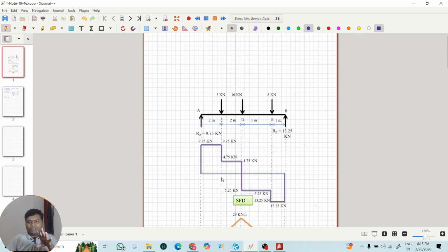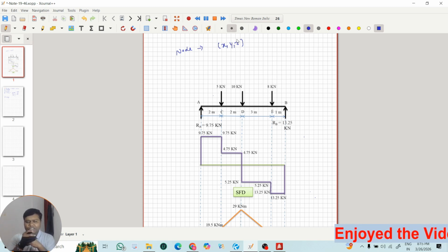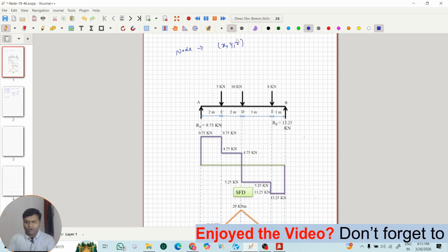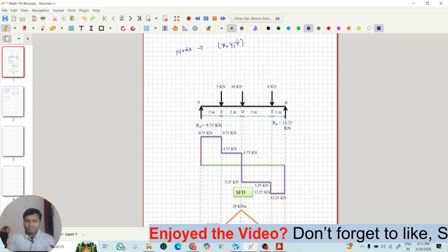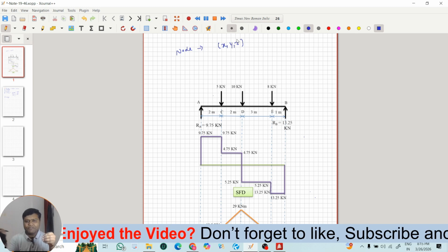So now, as we discussed in the last video, when we are starting the modeling, first we have to decide the nodes. Okay, and as per the STAAD Pro, every node has its coordinates, like x, y and z. So every node has coordinates in the x, y, z directions. So it means we have to decide the coordinates of all the structures. Okay, so if a large building or large model is there, in that case you can just start with the origin. You can just assign the origin and then we can model everything. Okay, that we will see one by one.